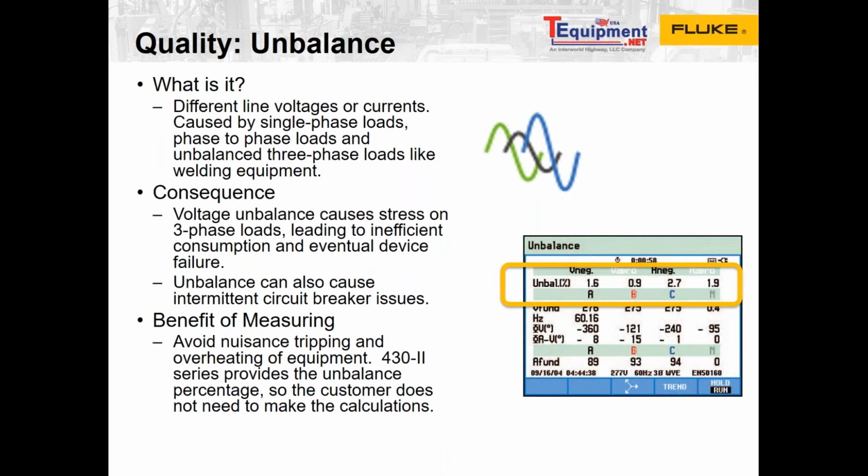And traditionally, I've seen people calculate it using the DMM. I think we already went through that example, but the Fluke tool will just calculate it for you in one shot, so you're not standing there. The other thing about taking the measurements with a DMM is that power quality and energy can shift. So when you make your first measurement with your DMM on the first phase, and then you go to the next phase and measure, something in power quality could have shifted between the time you took the first measurement and the second measurement and the third measurement for your 3 phases.